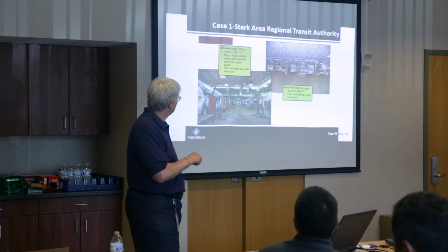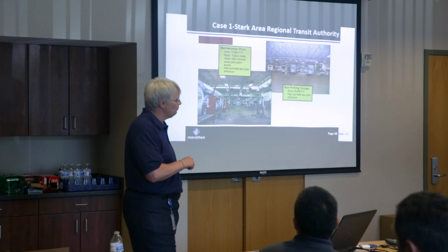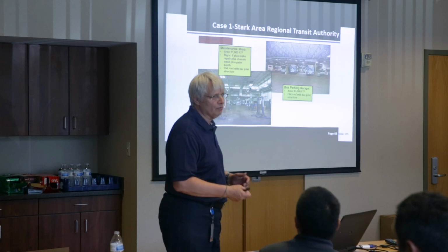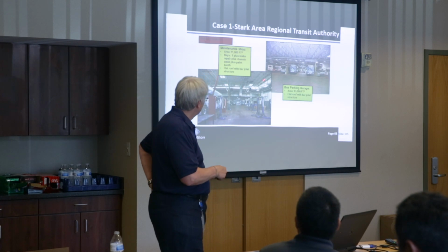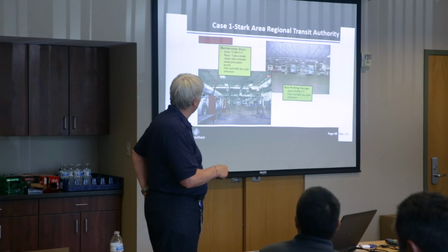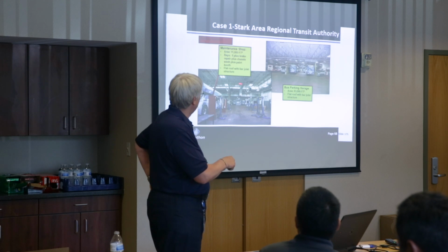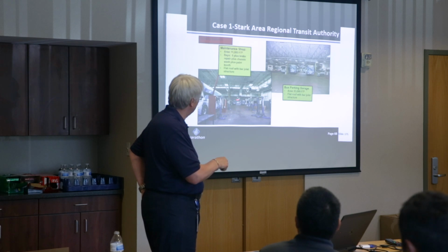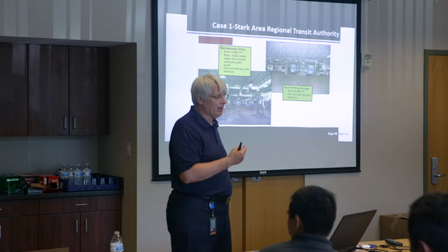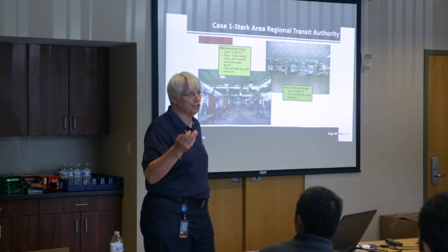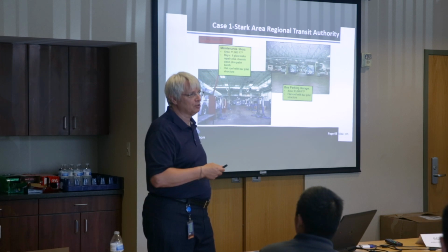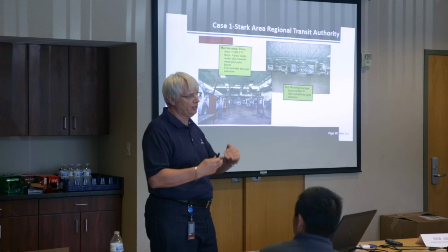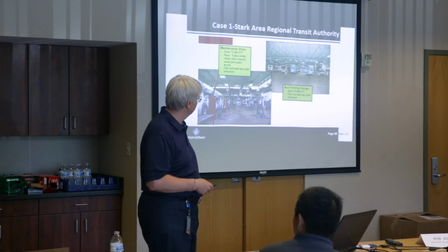You can see there is a step in the roof here, and why is that? Well, you need more headroom in the maintenance shop because you have to be able to put buses on the lift. So that part of the shop is higher. And again, the 18-inch zone that we talked about, the way we apply it, it would apply both in this area as well as in the other area. And when you get out there, that makes sense because the parking garage is huge compared to the maintenance shop. So really, they are almost separate areas even though they're directly connected at the end of the wall.